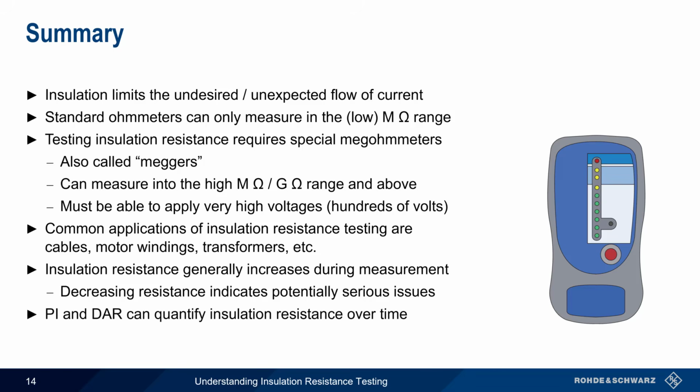And finally, we briefly discussed polarization index and dielectric absorption ratio, which are both used to numerically quantify this change in insulation resistance during the measurement time. This concludes our presentation, Understanding Insulation Resistance Testing.